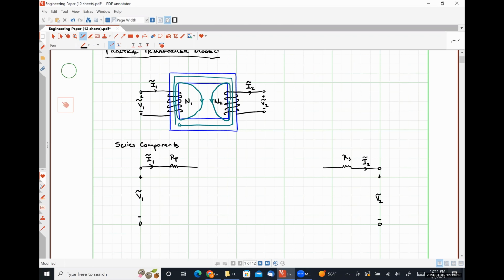From our initial diagram, we can see that not all of the flux that passes through the primary coil links to the secondary coil and vice versa. This leakage flux is a form of inefficiency in the system, but does not represent a true loss, meaning we're not going to see any power losses because any energy that's stored gets transferred back and forth. So to best account for this leakage flux, we are going to include some inductive reactances: jX sub P in our primary, and jX sub S in our secondary. And let's go ahead and take care of these as well.